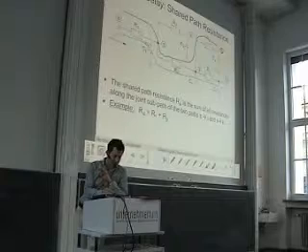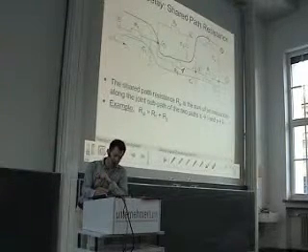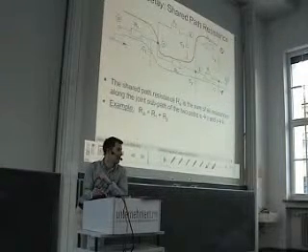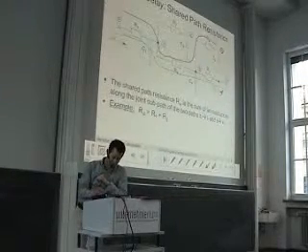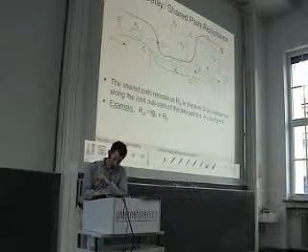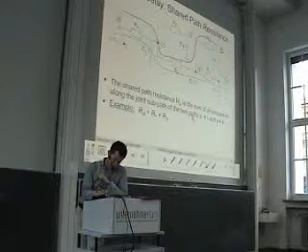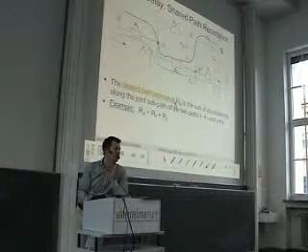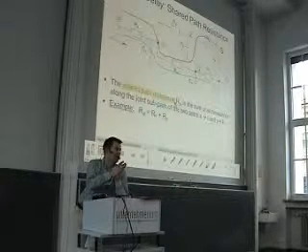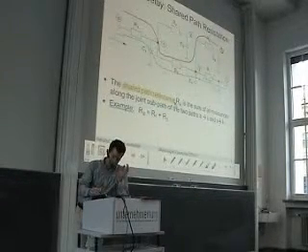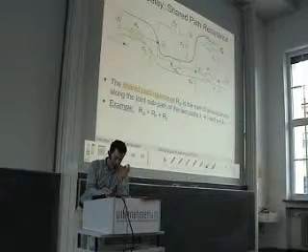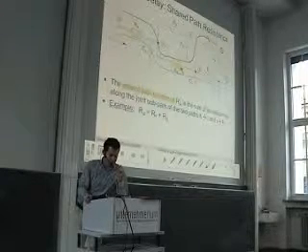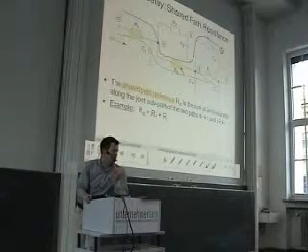This is this subpath. And then there is a subpath that belongs only to the red or only to the green path. So the joint path resistance, or shared path resistance, is the sum of all resistors that lie in the common part of both paths. So we have this resistor and this resistor that belong to both paths, and hence they sum up to the shared path resistance.